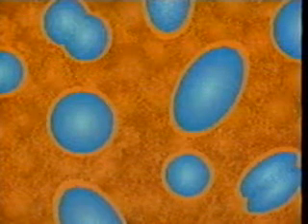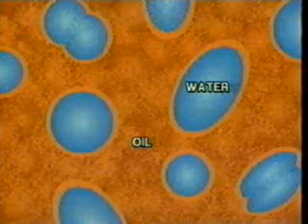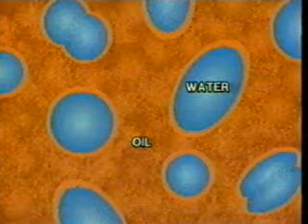Now, some of the water in the wellhead fluid separates easily from the oil, thus it's called free water. But the rest of the water is mixed so completely, or emulsified, that treating is necessary to remove it from the oil. In an emulsion, one of the liquids is spread out, or dispersed, throughout the other in the form of small droplets. In oil field emulsions, water is usually dispersed in oil, often called a water-in-oil emulsion. Now, the opposite, oil-in-water emulsion, can also occur. Depending upon the type and amount of emulsifying agent present, an emulsion may be easy to break, or loose, or it may be hard to break, or tight.